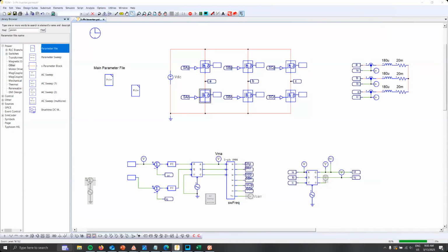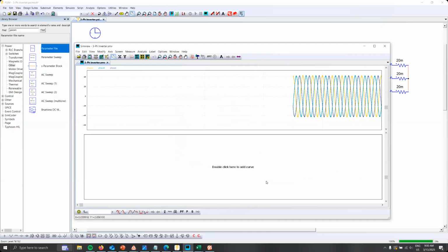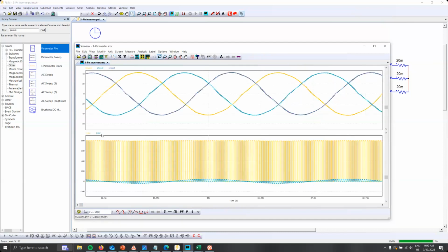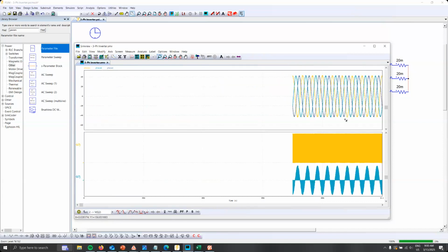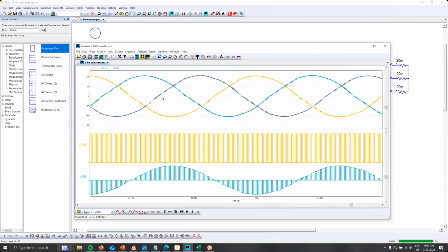If you want to get into the dV/dt, dI/dt interactions, you should look at using the level 2 models, which is a different topic. But soft switching can still be properly modeled, because we basically put an external capacitor onto the model, and that allows us to look at the resonance in the soft switching.